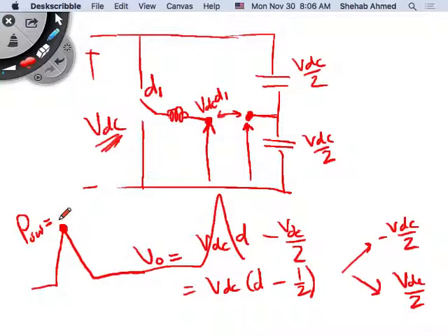So it's an optimization process, right? Do you want to live with 4 switches for a full bridge inverter and use less voltage? Or do you want to live with a half bridge inverter and use 2 switches, but then increase the voltage at the input, which means you increase the switching losses? If you increase the switching losses, you may need a heatsink, right?